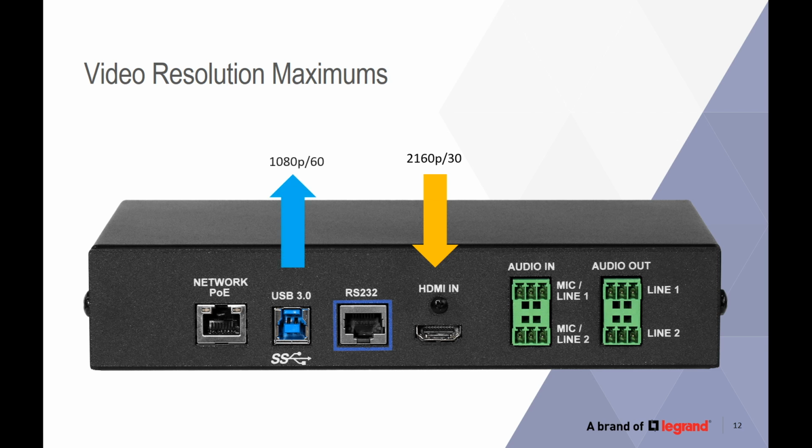Yes. Output on the USB, because we are using uncompressed YUV and we get the extra bandwidth the USB 3 provides, we get up to 1080p60 uncompressed video. Super smooth. Yes, super smooth. Beautiful video. And then 1080p30 available over the IP streaming. We are using H.264 encoding in case you're curious about all that, but up to 1080p30, and that is configurable in the web interface.